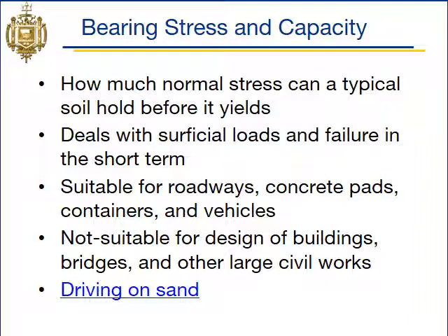So the types of structures or analysis we'd see would be bearing capacity for roadways, bearing capacity of subgrade for concrete pads, bearing capacity of soils where we're going to put some containers, and maybe bearing capacity for some area where we're going to put vehicles. Bearing capacity and bearing stress is not really a suitable method to determine how strong a soil is for the design of buildings or bridges or other large pieces of civil works.